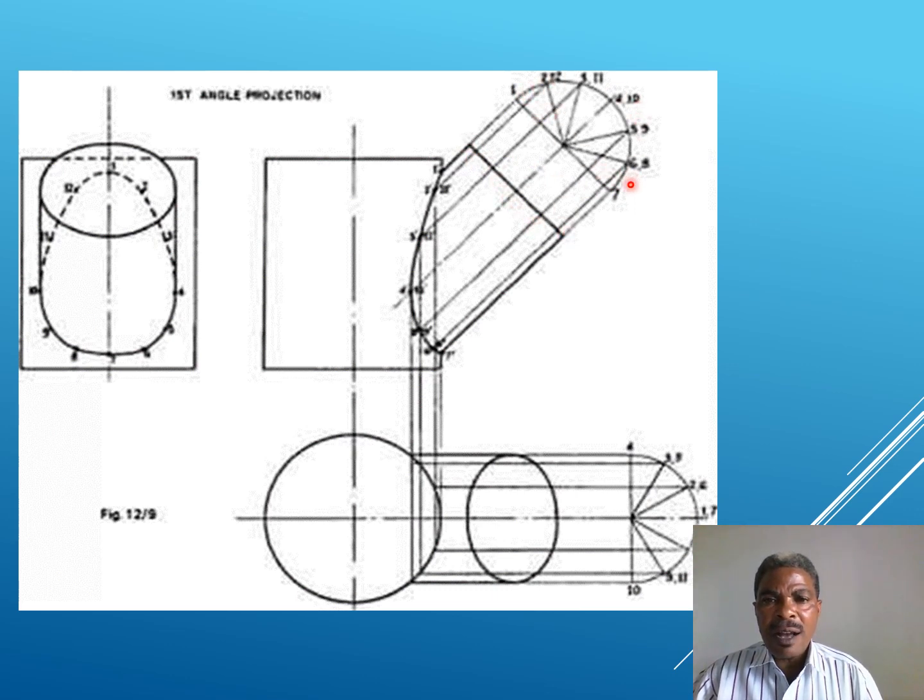The half circle is to be divided into 12 equal parts, or 8, depending on your interest. In this case, it is divided into 12. If this semicircle for the front view is labeled like this, the same procedures will be conducted for the plan view.